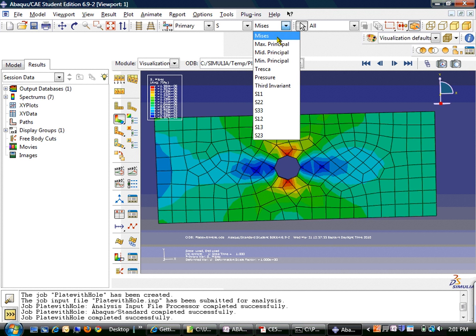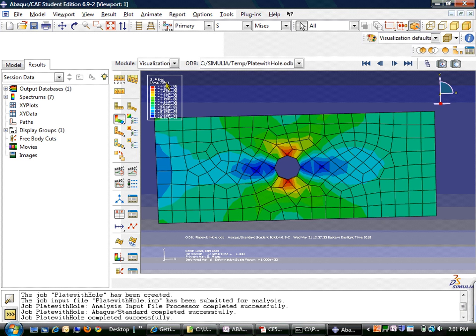Okay, so the von Mises stress is used for plasticity problems. This is a stress such that when you reach this von Mises stress, your material at that point might start to yield. In this case, what is plotted here is von Mises stresses, and you can see that this red region at the top of this curve has the highest positive stress, that is tensile. And the blue region, can't tell whether this is positive or negative. It looks like a very small number, so it's close to 0.